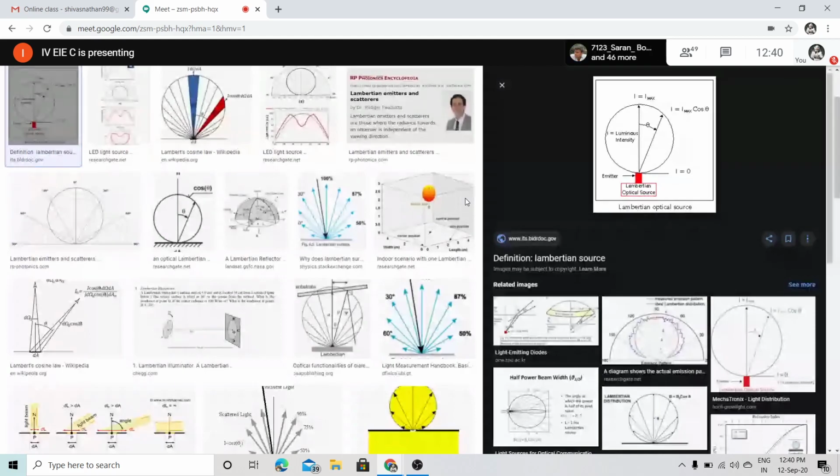Now the fringe pattern is not about the refractive index, and not about any other parameters. The fringe displacement is about the distance that is covered. The laser energy which is focused and split into reference and active beams meets again at the beam joiner, and you will see an interference pattern created, which corresponds to my photodetector. So if I map my interference displacement value to the photodetector, I could easily measure the distance covered. Clear? This is how the measurement of length takes place.